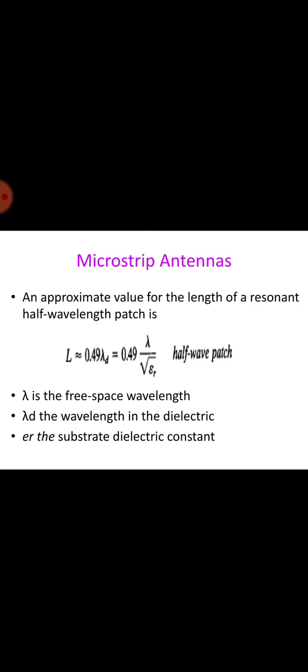This model suggests an aperture field analysis approach where the patch has two radiating slot apertures with the electric fields in the plane of the patch. For the half-wave patch case, the slots are equal in magnitude and phase, and the fields along the edges associated with slots 1 and 2 are constant, whereas those along the other edges seen in this side view have odd symmetry and their radiation cancels in the broadside direction and is usually neglected.